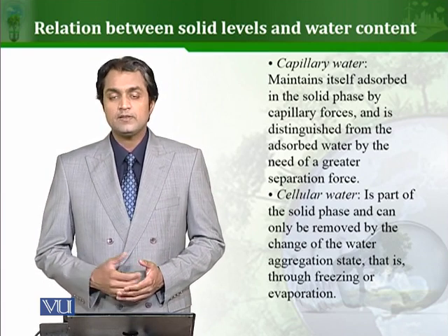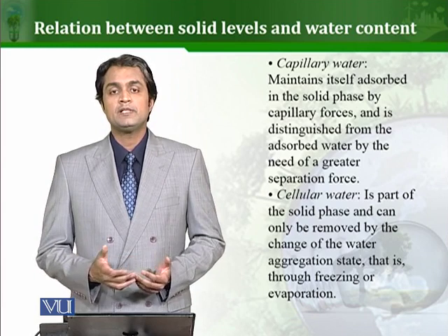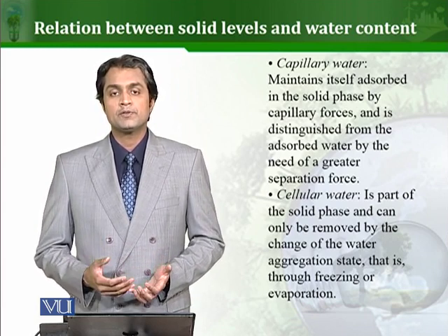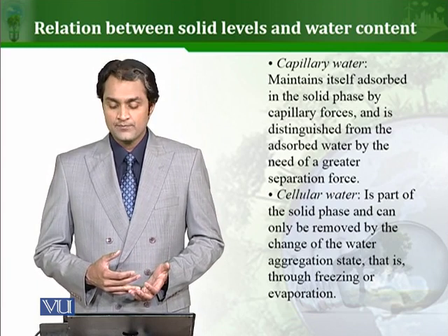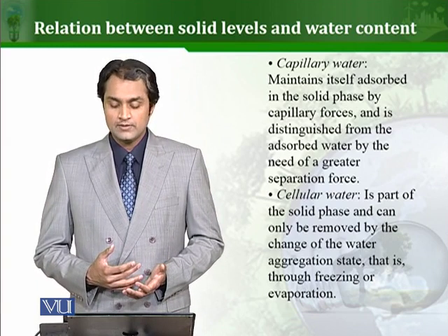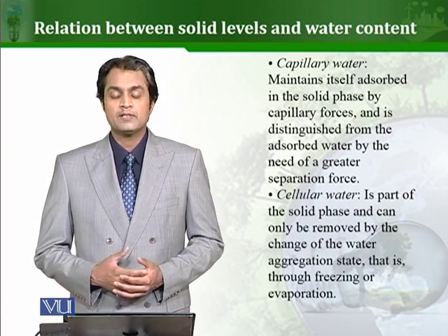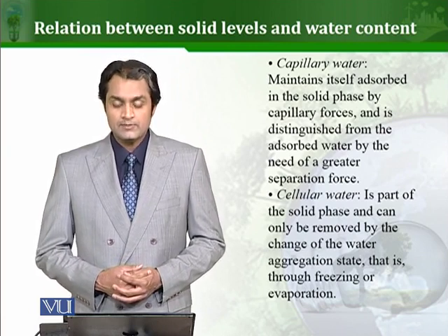So again you can see here that different types of sludge will have different ratios and different proportions of water. They may have free water, adsorbed water, capillary water and cellular water. There are different ways to remove each one. Again it depends on the type of the sludge. I will see you in the next lessons.